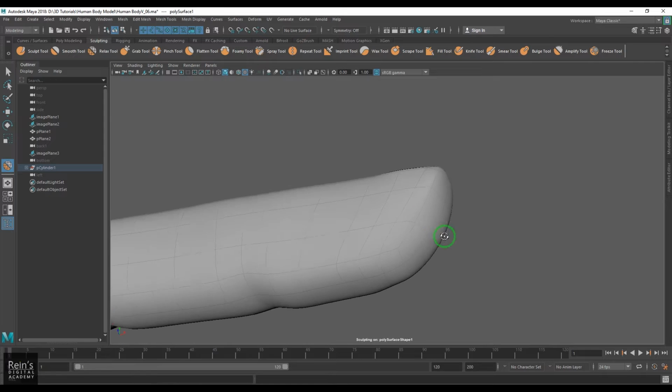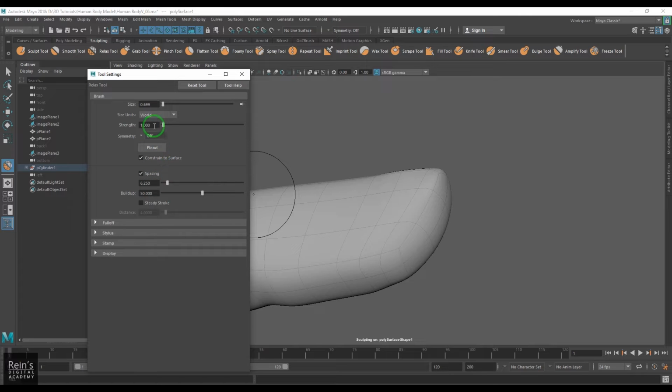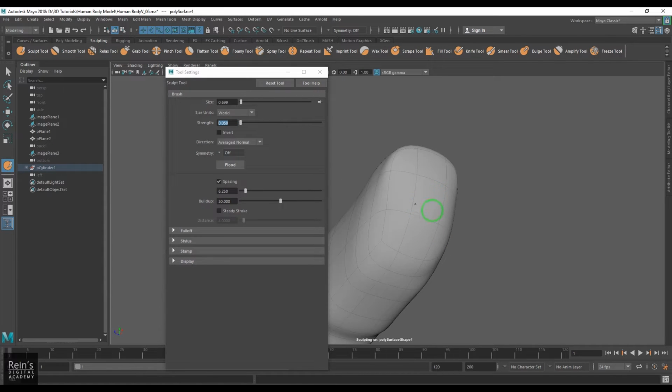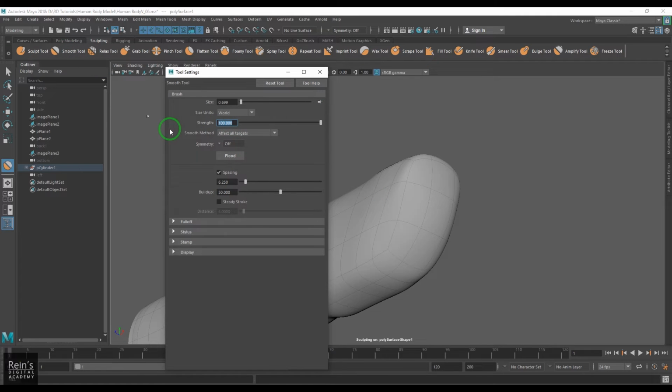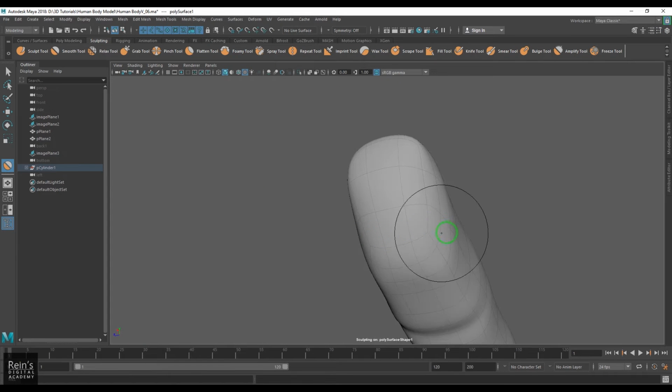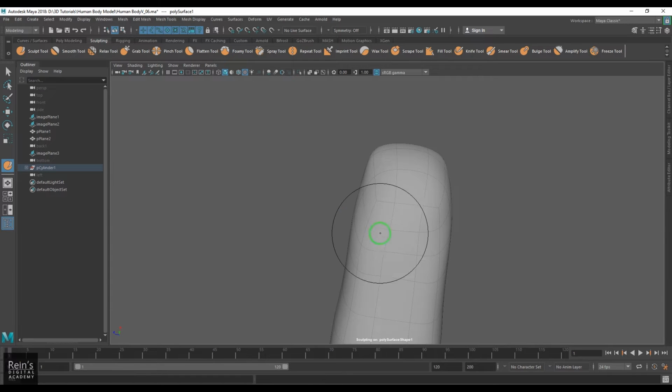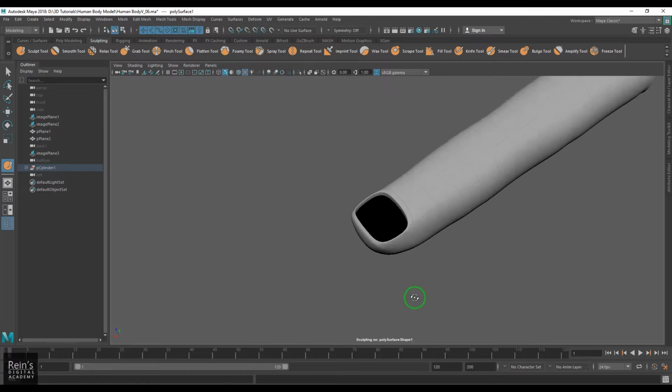You can use the sculpt tool and start sculpting those faces. So the sculpt tool with a strength of 0.05, let's see. Yeah, it's doing some real quick. So let me select the smooth. The strength of the smooth is 100. Let me put it to 20 and then do it gradually. So use a combination of sculpt tools and then give that nice volume.